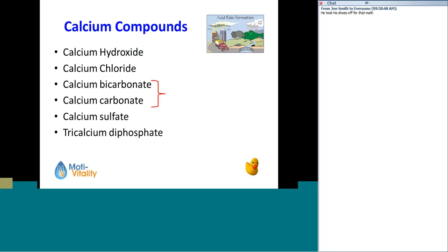When that falls down to the ground, it dissolves the rock in the ground, the calcium carbonate, or CaCO3, and it becomes calcium bicarbonate. So calcium bicarbonate is dissolved hardness. When the water heats up, the carbon dioxide leaves the water and causes the reformation of CaCO3, or scale buildup.